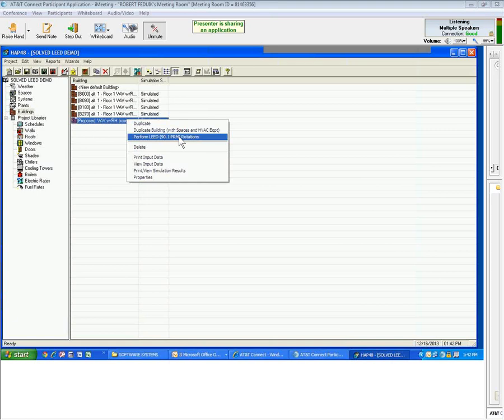And remember, when you rotate the building, it's not symmetrical typically. You get different airflows. You get different loads. So the minimally compliant baseline EER and COP may be changing as the loads change. And this perfectly lends itself to computer. All that will be figured out for you. And it'll just populate the LEED report with all the correct EERs and COPs and all. So HAP is used extensively.